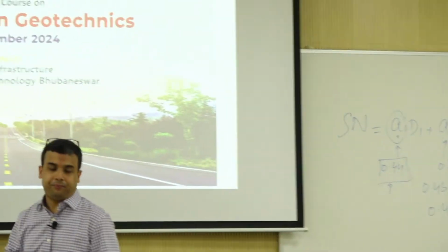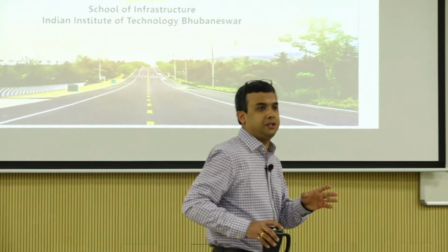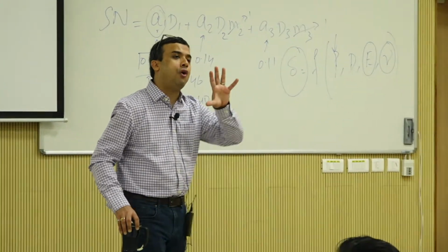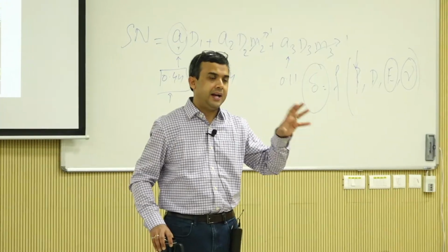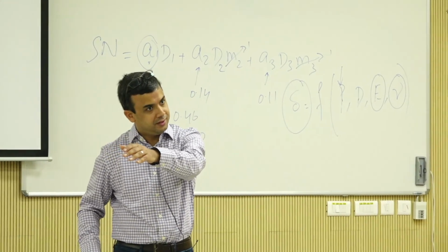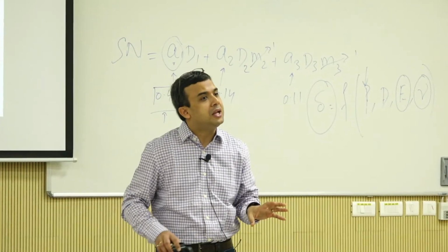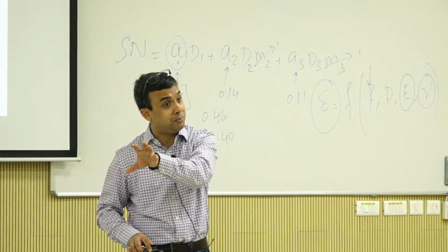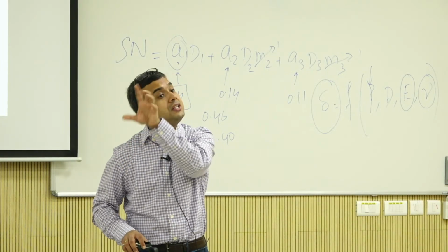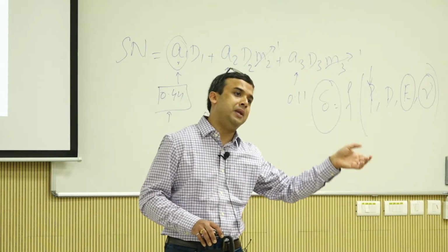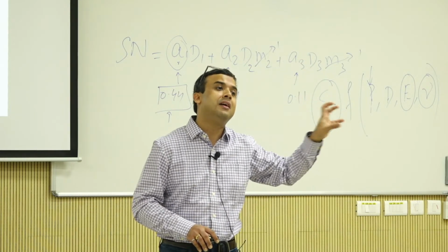Okay, so good question. A forward calculation is basically when you have all your properties and you are trying to determine response. Okay, a back calculation is you are missing some property but you have some response measurement. So now you are using the response and some other properties to back calculate, or to determine, the missing component.